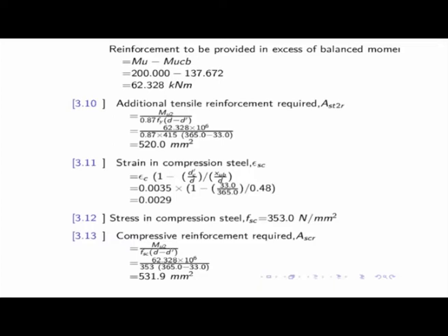The issue is whether you will believe your calculation or not. Obviously I do believe my calculation, and on the basis of whatever value I am getting, in this case I can use 12 millimeter dia bar, and I shall pay for 5 numbers of 12 millimeter dia bar, because the cross sectional area of each 12 millimeter dia bar is 113 square millimeter.